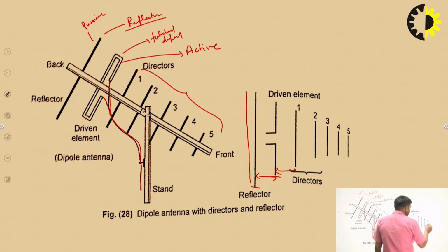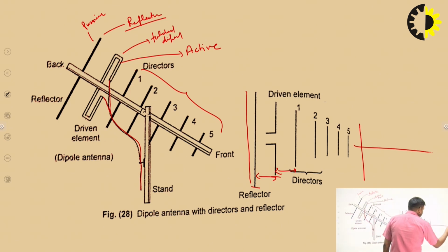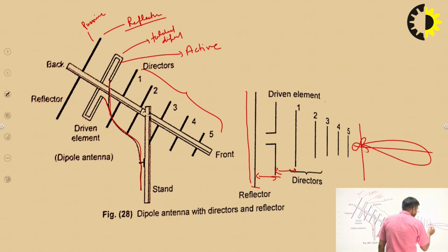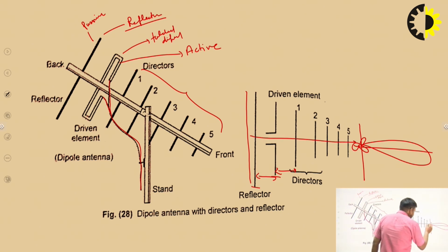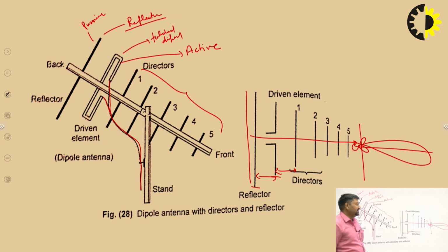The radiation pattern of this antenna is unidirectional, where the directivity, or half power beamwidth, is maximized in the direction of the antenna array axis. So this is the antenna array axis, and we can say this type of antenna is also called an end fire array antenna. We discuss here how we design this antenna and what the applications of this antenna are.